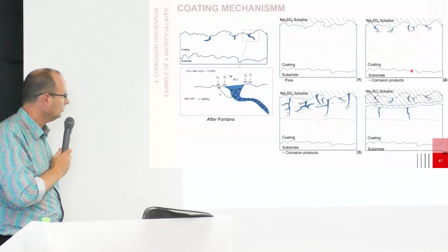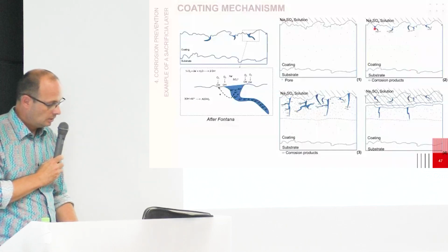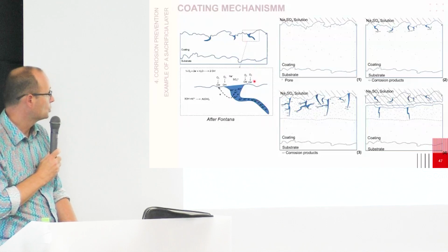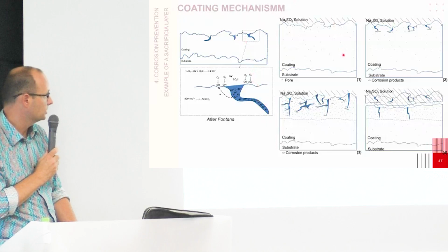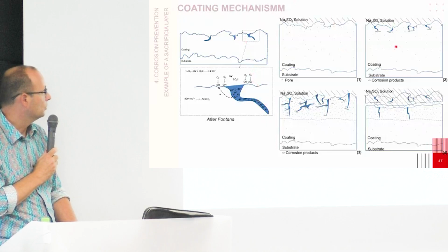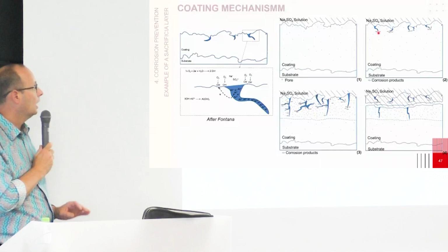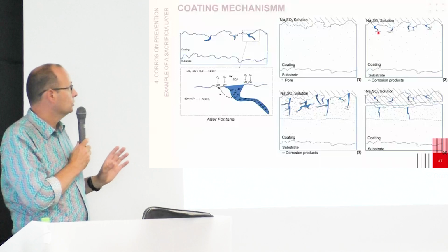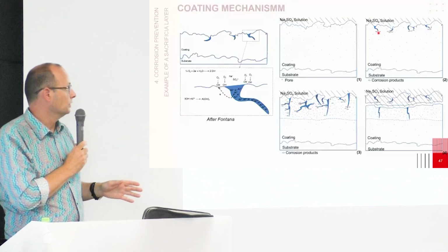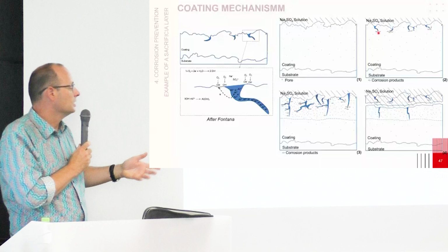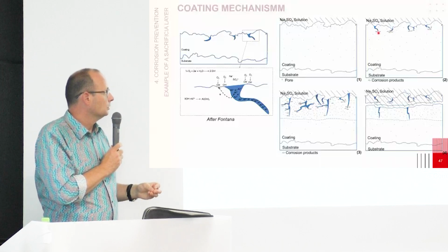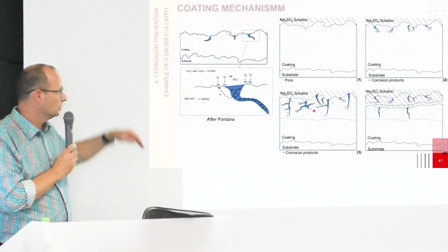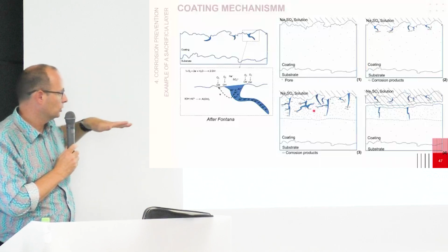However, from the basic and first mechanisms of corrosion, and from the observations that she has made, she found that there is at least some specific diffusion path, and the water goes through this specific path, destroying the adhesion between particles, and moves not only in the depth of the coating, but also laterally.